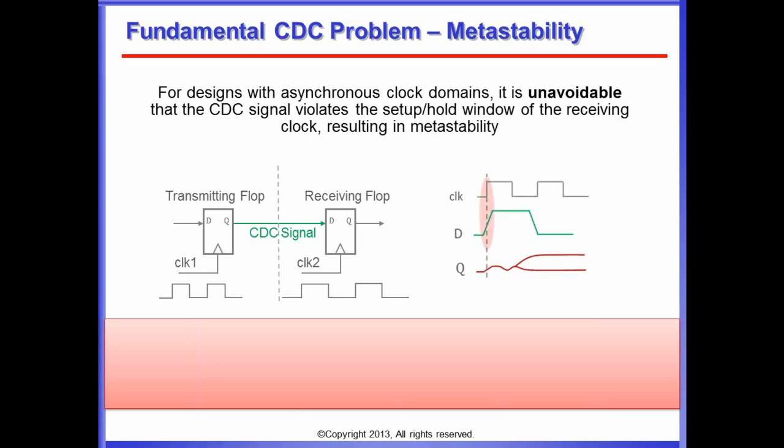This swing propagates as, let's say, an unknown through the design. You have to capture it up front, and with an asynchronous clock domain crossing, you will always somewhere get those, because you never know when data and clock show up exactly.